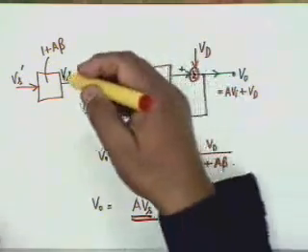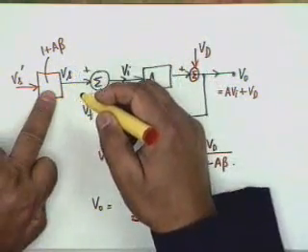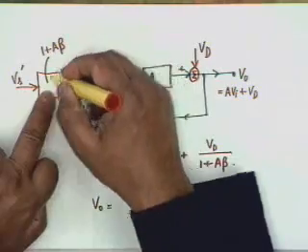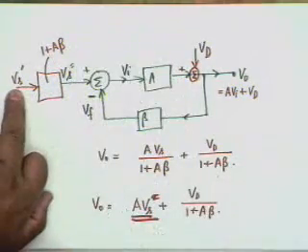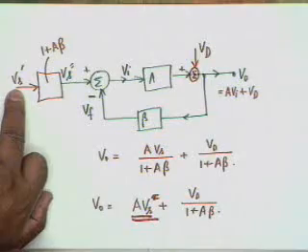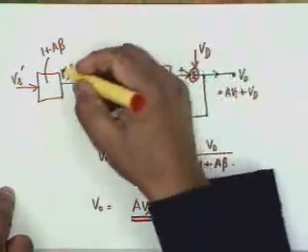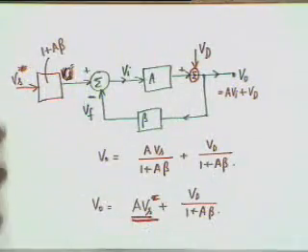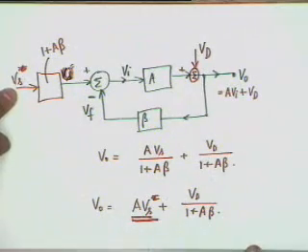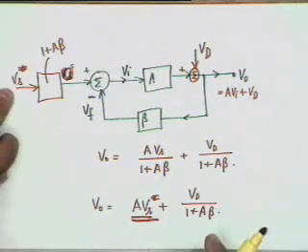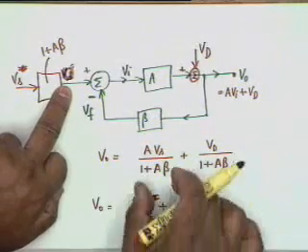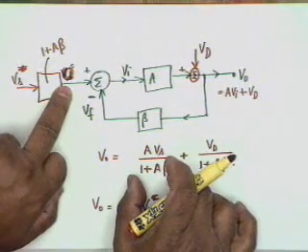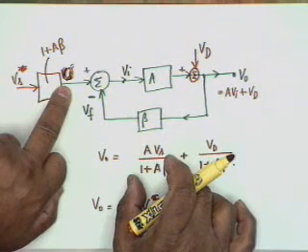Okay? There is no distortion here, and therefore this voltage Vs is equal to Vs prime multiplied by 1 plus A beta. Alright? That is all the change. The output should be Vs prime. Okay. So what we do here is we consider this as Vs. Is it okay now? We have applied, instead of Vs, 1 plus A beta times Vs. Okay? Is the difficulty taken care of?